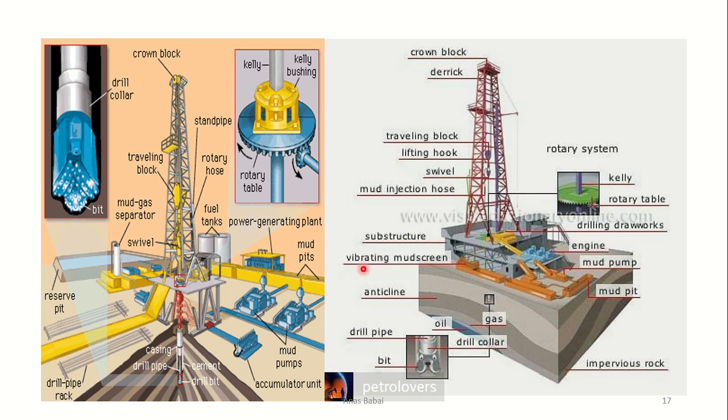We have a vibrating mud screen, in which we collect the drilling fluids from the borehole and separate the drilling fluid from the cutting samples, because this drilling fluid is circulated once again to the mud pit and then the mud pump, and goes in a continuous circle through the wellbore.